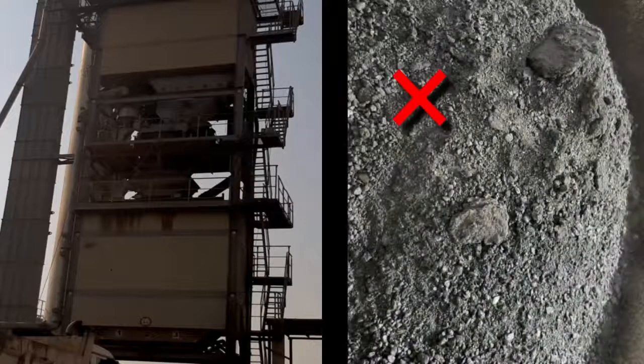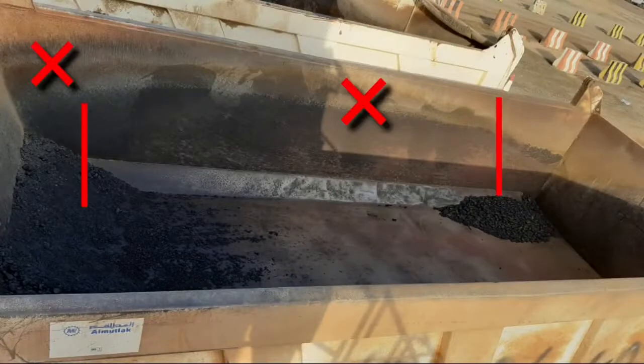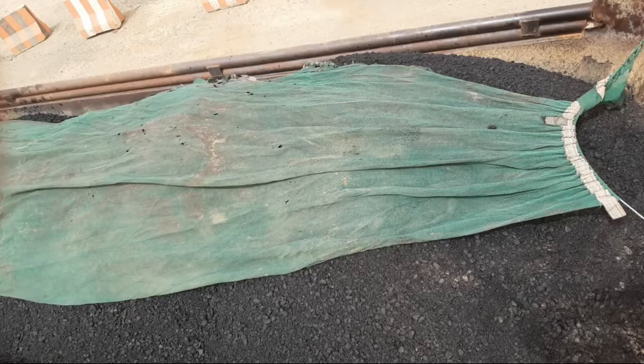Before starting the mixing, ensure that mixing unit is clean from inside and there is no hardened asphalt inside the mixing unit and discharge unit downside. Selection of trucks. All trucks should be cleaned by diesel and there should not be hardened asphalt inside the truck. All extra diesel should be removed from the truck. All trucks should have tarpaulin to cover the asphalt after loading.